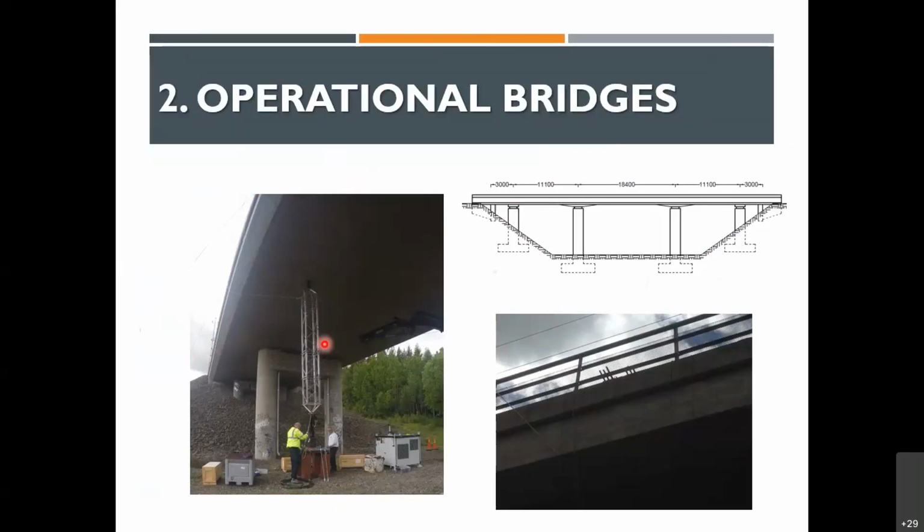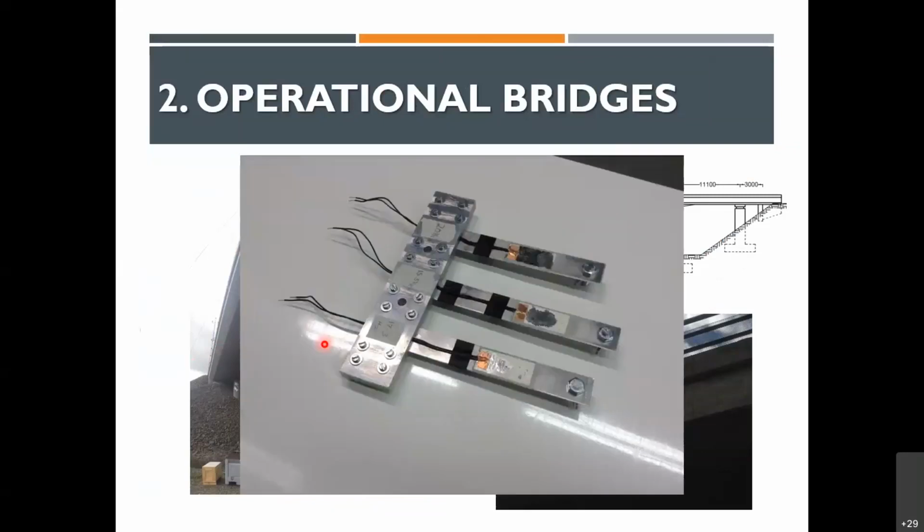But anyway, long story short, that was the type of harvester that we made. And so you can see the piezoelectrics here. Those masses could be changed along this groove so that we manage its natural frequency. We had an idea about the range of natural frequency. So we put the central frequency and then essentially distributed the 6 frequencies of the 6 harvesters on the left and right hand side of the first bending frequency that we found from finite element modeling and the differential equation based modeling.